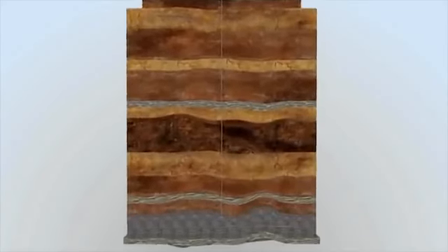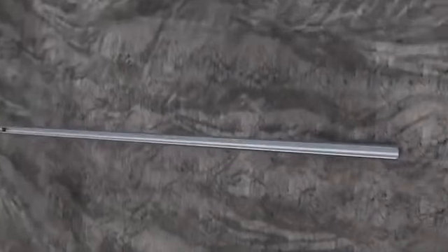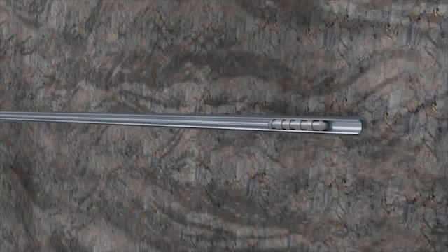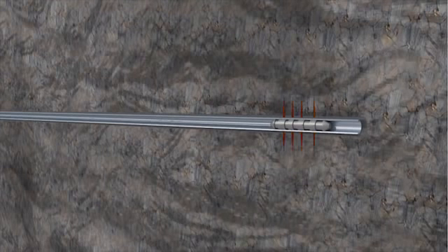The first step in completing a well is the creation of a connection between the final casing and the reservoir rock. This consists of lowering a specialized tool called a perforating gun, which is equipped with shaped explosive charges, down to the rock layer containing oil or natural gas. This perforating gun is then fired, which creates holes through the casing, cement, and into the target rock. These perforating holes connect the reservoir and the wellbore.